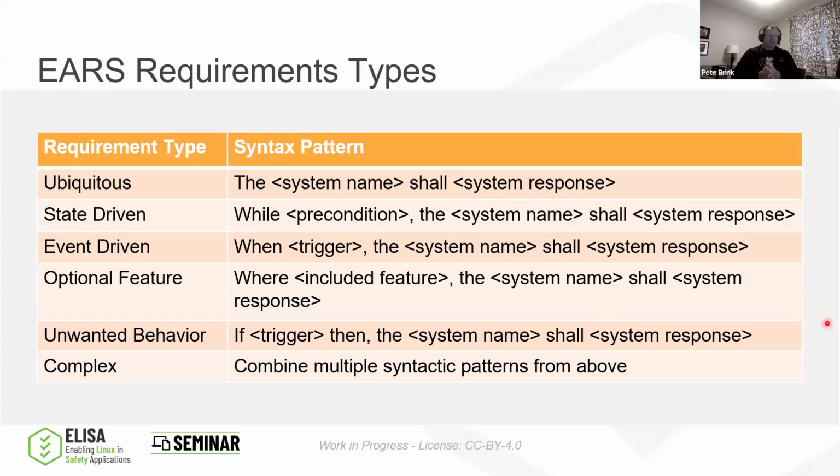So keeping in mind that we're talking about a hierarchy of requirements, the first of those, where you talked about having an external fuel tank, is really applicable at the system level. The knowledge that that external fuel tank is there would cascade down through all of the requirements that are then applicable to that version of the aircraft itself. Whereas when we talk about the debug versus release mode, we're really talking about the software for a specific release that goes into a specific electronic control unit on the aircraft itself.